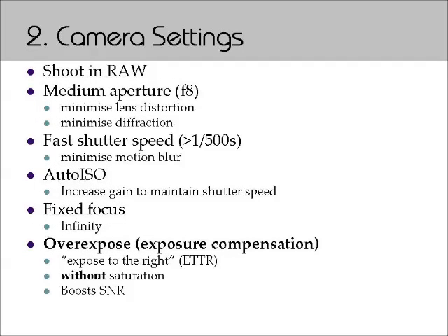But there are some big takeaways here. Firstly, bigger pixels means more light, but less detail. You're going to have that trade-off in anything you do, more light versus less detail. So if you take more light in, you get a better signal-to-noise ratio, and you'll generally get a better dynamic range for the camera, which means better imagery, but you will get less detail.